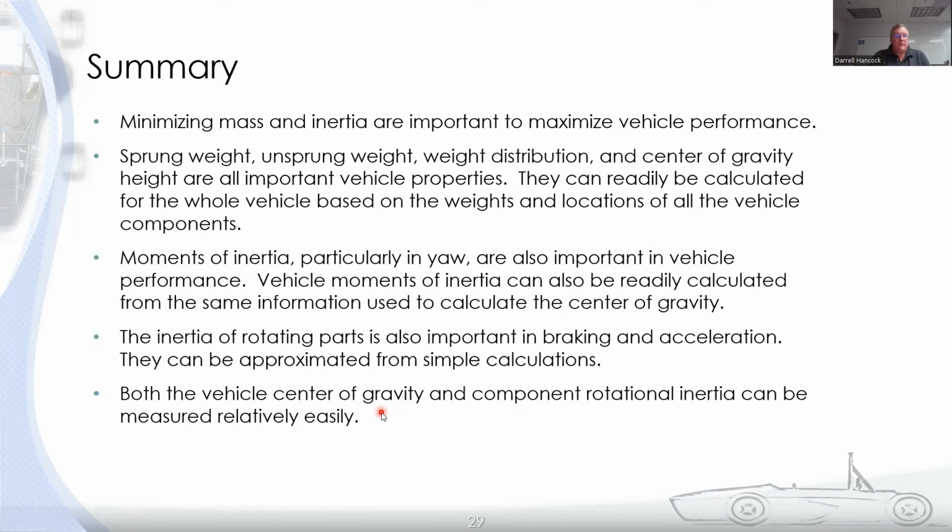I think virtually every team will have 4-wheel scales. You just need some means to elevate 2 of those scales to measure center of gravity height. And that bifilar pendulum is something you can easily make from some scrap materials in your shop.